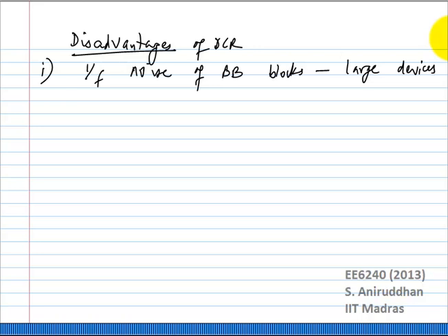Correct. The assumption is that when you actually do a super heterodyne kind of receiver, since you have more intermediate processing stages, you're also amplifying correspondingly. So the signal is already large enough at that point where you don't need to use very large devices. Because really here in this case you're getting gain primarily only from the LNA, maybe a little bit from a mixer. Okay. Any other issues? Similar to 1 over F noise.